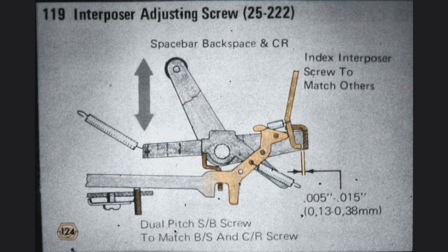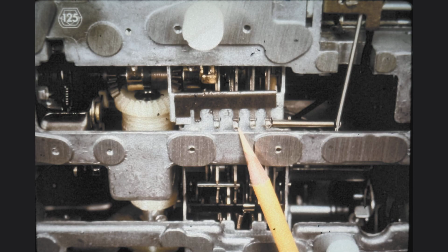The adjustment is performed by allowing the rear of the interposer to come down when we want to increase the clearance between the latch and the cam follower, and by raising the rear of the interposer when we want to decrease this clearance. These are the screws which control the horizontal front-to-rear adjustment of the operational selector latches. They are located underneath the operational cage.